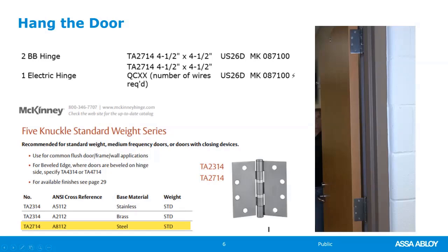Your electric raceway that will be drilled at the factory has a direct shot from the hinge to the electrified lock. When you're writing the specification, you don't need to identify the number of wires. When you're estimating this, you can figure it as a 12-wire hinge. It doesn't cost that much more than a 4-wire or 6-wire hinge. When you're detailing it, you would have to figure out how many wires are needed for the function of the lock and any monitoring that there is for that door.